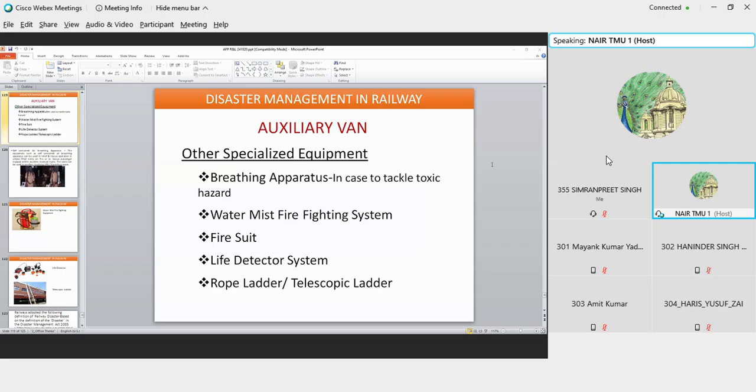The counterweights are used in this scenario because I have to balance the torque. I don't have space, so the outrigger which I am using for propping has 3 positions. In the maximum position, it is the most stable. But assuming that at the place where the accident has happened, I don't have sufficient place for the outriggers to reach full extended condition, I'll take it in one condition or the second condition itself.